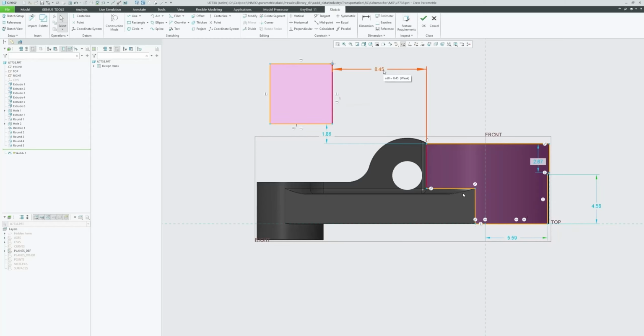And then if you move your mouse over any of the constraints or dimensions, it will highlight the references that are used inside those dimensions or the constraints for future reference. If you want to create your own dimensions, click on the dimension icon, select the items with the left click and then middle button where you want to place the dimension. You can then change the value, and what you'll see is that the weak dimension, the light blue dimension, will disappear.